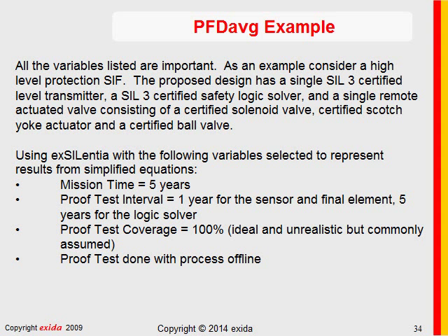Good question. Another question: how do you determine or calculate the effectiveness of a proof test? Oh, good. Well, that's a similar question as before. At exida, we use an FMEDA for any particular valve. Now we've done 200 or 300 of these, and we've seen very similar proof test coverages as a function of proof test type and as a function of the application environment.